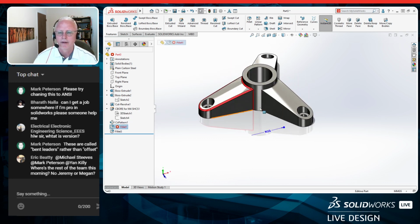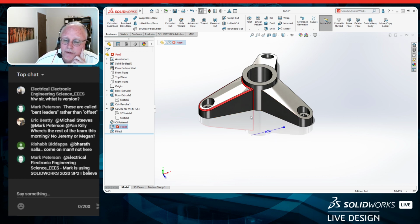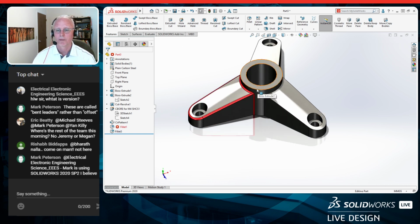Our fillet here, that's our 22 millimeter fillet. Okay, we're probably going to have some challenges there because how am I going to put a 22 mil or a 30? It's going to be 30 across those faces there. We'll have to do that. And obviously, this no longer runs around, so we can repair that.